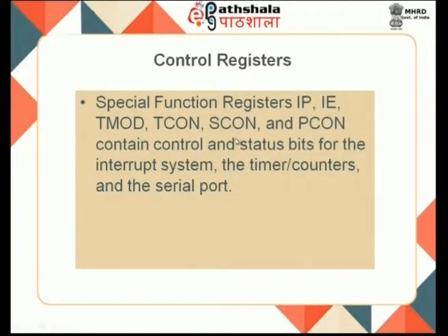TCON facilitates the timer mode as well as interrupt control, and SCON is meant for your serial communication register. So, IP, IE, TMOD, TCON, SCON and PCON are all control registers to support, enable and activate different processes which should be handled by your 8051 controller.